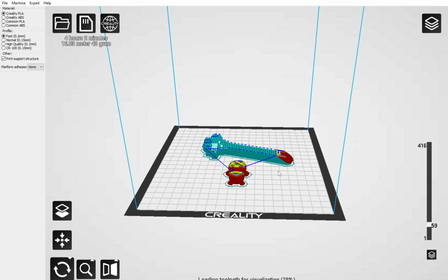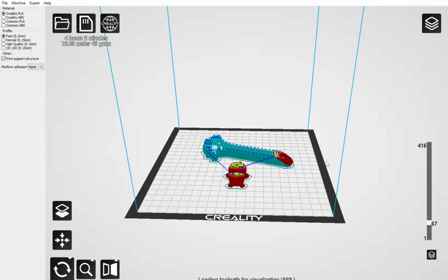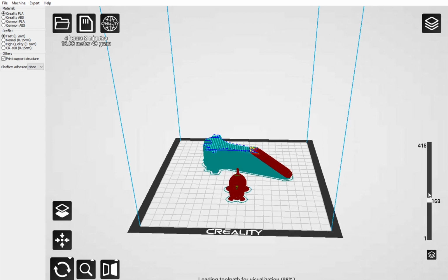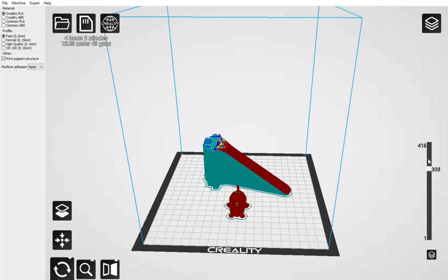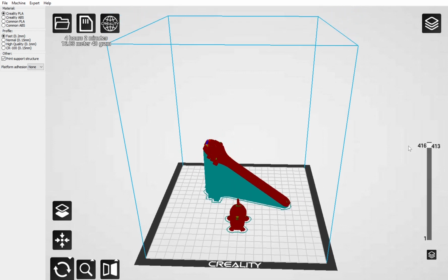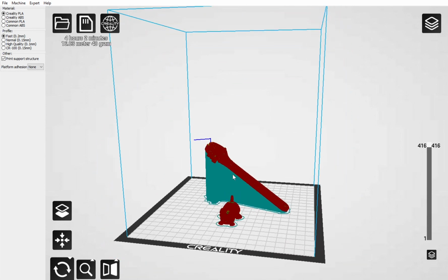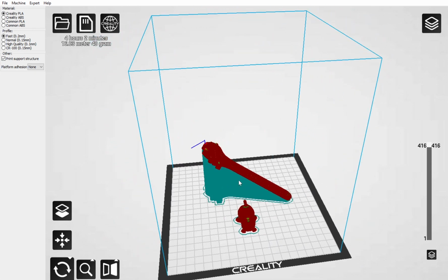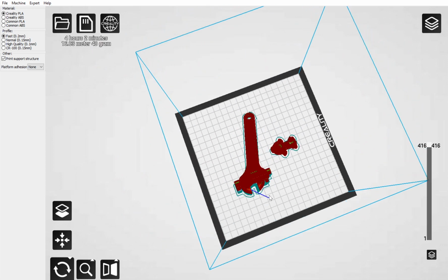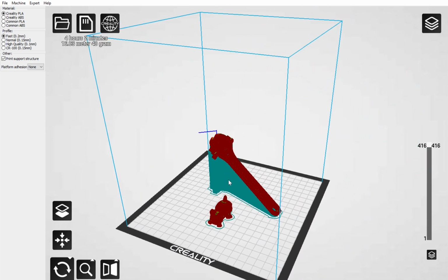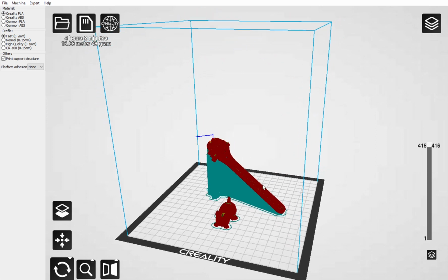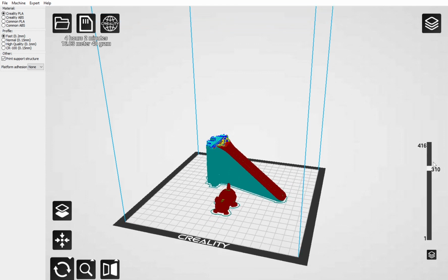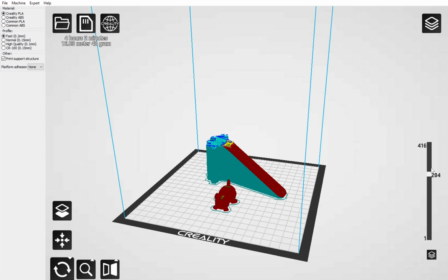So you can see the light blue underneath the wrench there is purely support structure, and that is not what we want because it's a waste of material. And yeah, the aim with all 3D printing really is to minimize the support structure and only include it where absolutely necessary. So there is some art to designing models that will be 3D printed. Avoiding it is not possible every time. Sometimes you need it, but there are tricks in the trade to overcome that through smart design, which is a common challenge across all 3D printing mediums.